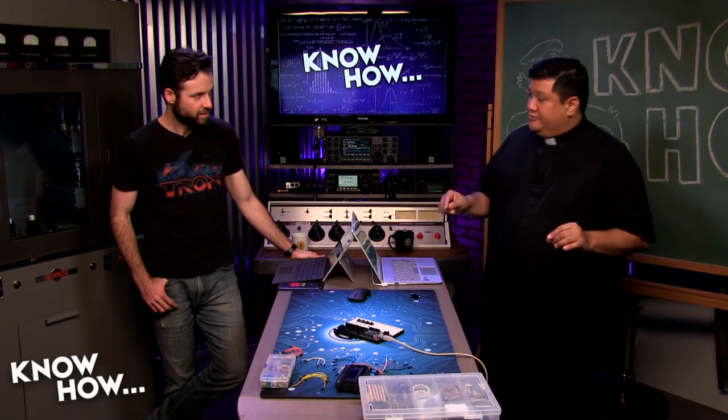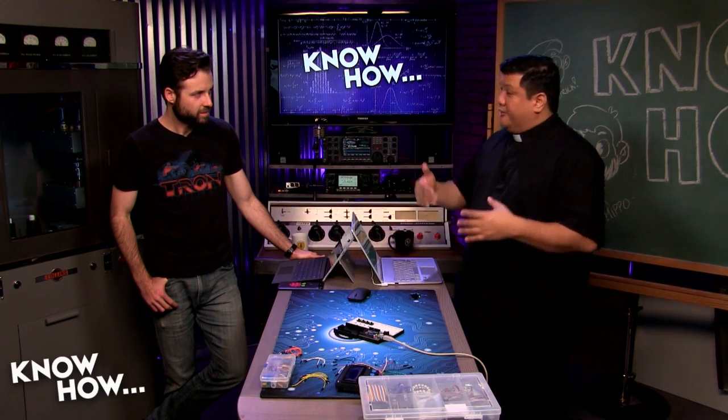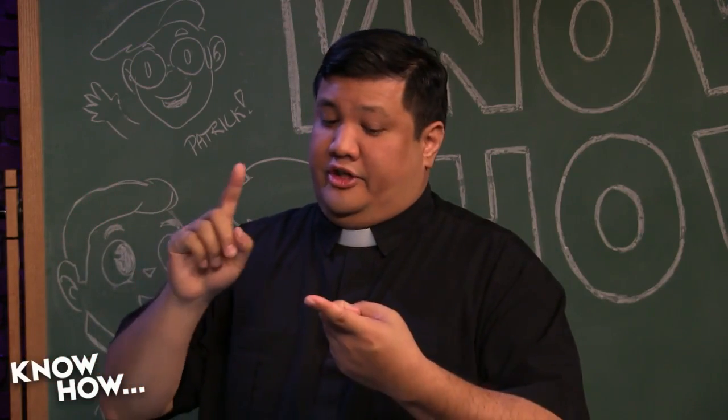So what we need, as we learned last week when we played with I2C devices, is there's always 4 pins. There's going to be the ground, there's going to be the voltage, which in this case will take either 3.3 or 5 volts. This is one of the adaptable screens. Some of the OLEDs really don't like 5 volts. This one will do it. Then you need a data line and you need a clock line. This one has one more line that's kind of optional. I always throw it in just because sometimes you get in a weird state where it helps. It's the reset line. And we're going to show you how to wire that up.